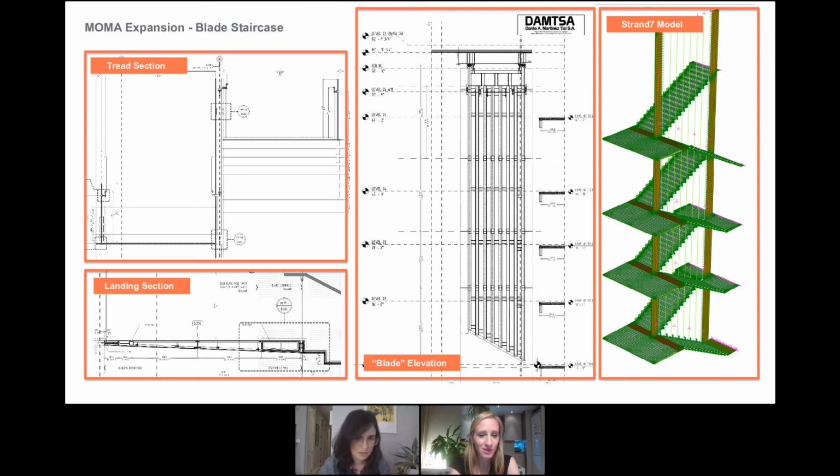How do you model a blast analysis in terms of the vibration? Well, you have a force, you figure out what your loading function is over time, and then you apply that to a finite element analysis of your glass, which was a glass fin system, and you just see what happens.